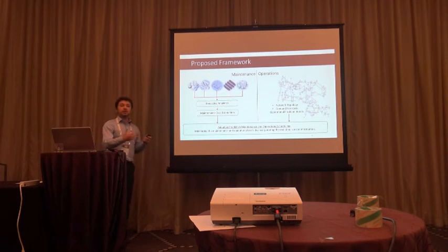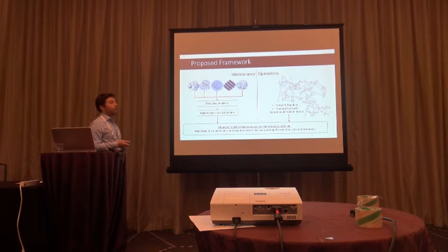So I guess the best way to start is to see a very holistic view of what it is that we are proposing. We have a number of generators, a number of power plants that are operating in the field. Everything you see in red is happening in real time. The real-time sensory information coming from these power plants is feeding into what we call a periodic predictive analytics phase, where we use the sensory information to understand the specific failure characteristics for those generators. That feeds into a dynamic maintenance cost function, which will feed into a fleet scheduling policy that will also include both maintenance inputs, the sensory inputs coming from the maintenance, but also the inputs that are coming from the operational side of things, including network topology and demand forecasts.